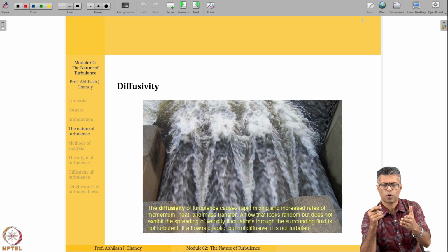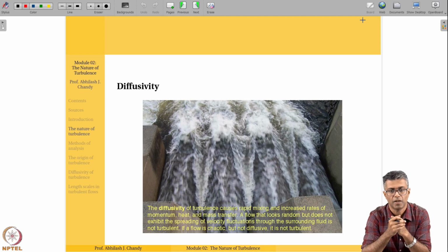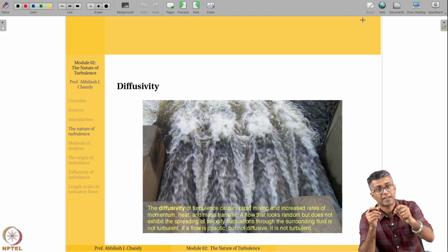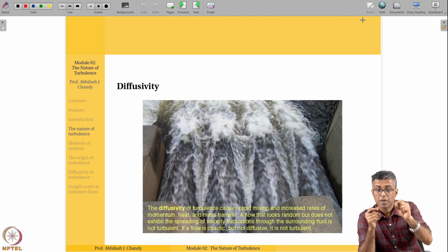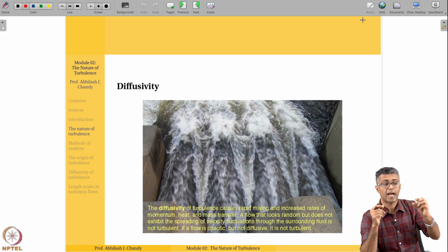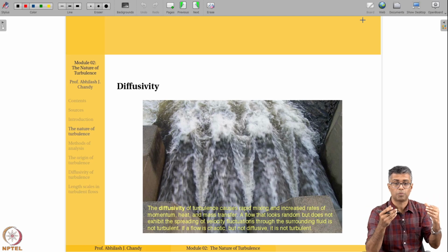Now, why does that happen? The water vapor from the exhaust of the aircraft is condensing, and that is causing that white smoke-like behavior. The fact that it is extending for miles means maybe near the jet, near the exhaust, they are turbulent. So they are probably generated turbulent. However, they are not turbulent over the miles that you see them. They might look turbulent to us.